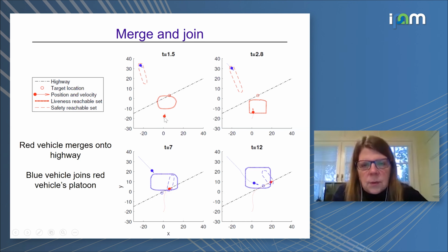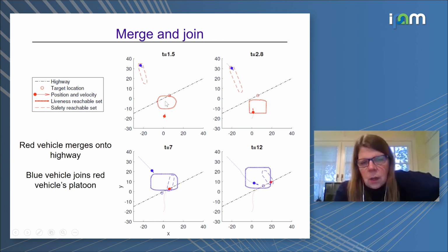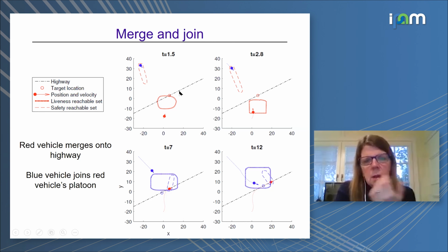From the perspective of the red vehicle, it is trying to get to this moving target along the highway. The control law is basically that it has to get to this particular region in which a predefined control law will snap it onto this moving target. So this becomes the region that it would like to reach. And then it detects the other vehicle. The region around that vehicle represents its avoid region. So this is the reach region, and this is the avoid region.